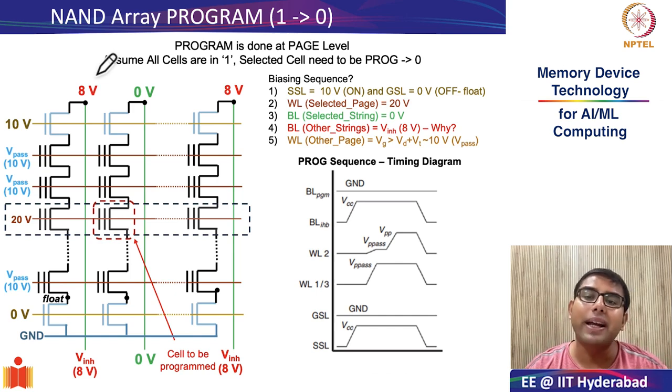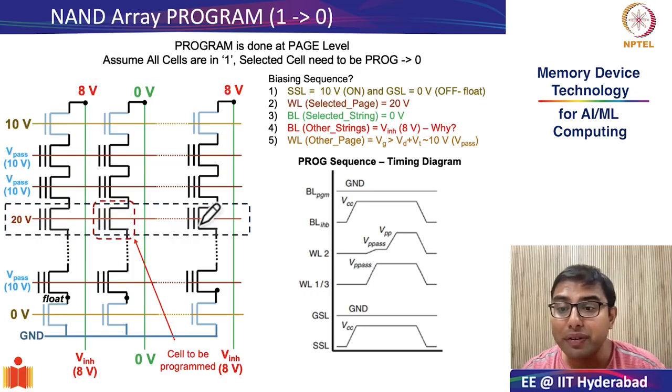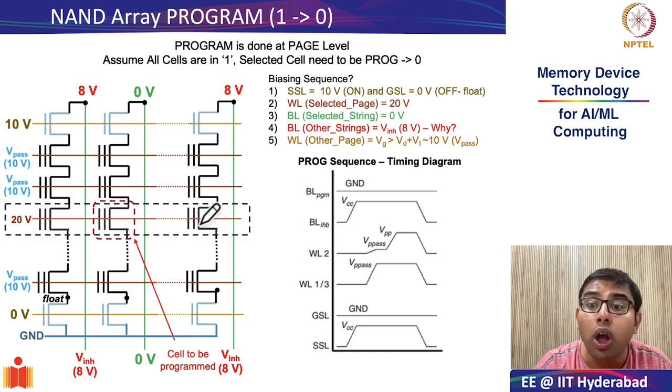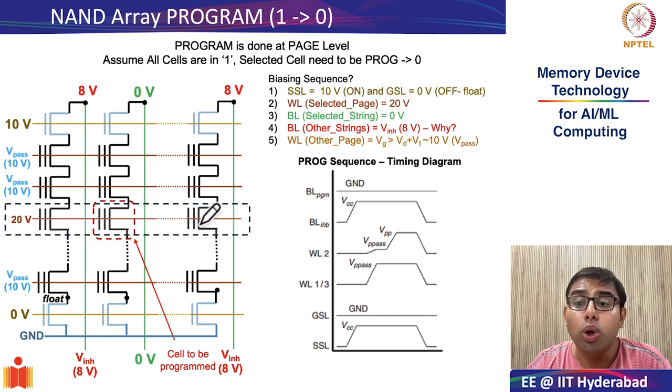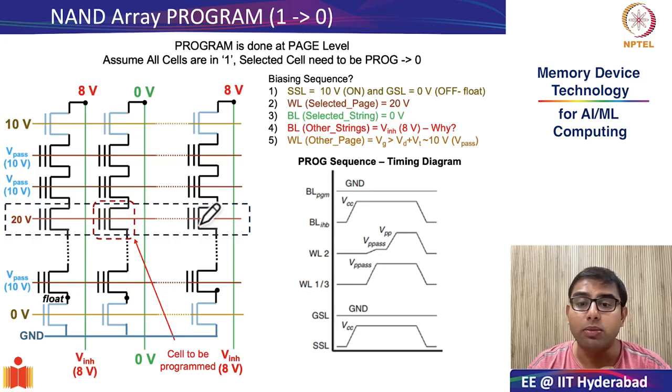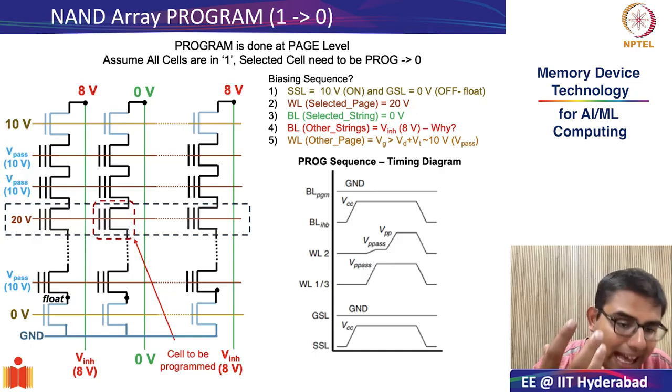One very important aspect I did not really emphasize in the previous class was to appreciate that during the NAND flash operation, especially program operation, it may not look in this particular diagram that a huge amount of data is being programmed, but this is not the case. Please remember, generally in a page, there are close to 64K to 512K bit lines. So at a time, you are programming 64,000 to 512K bits at a time, and this is what makes the NAND flash array architecture very, very special.